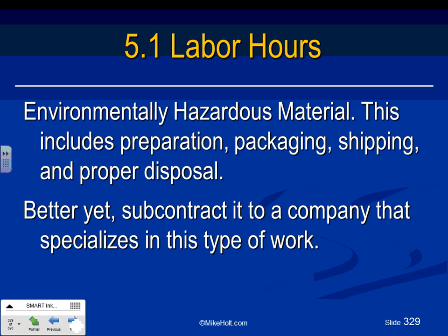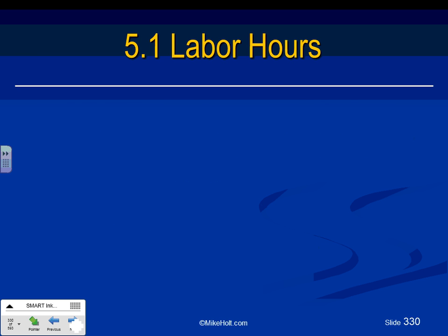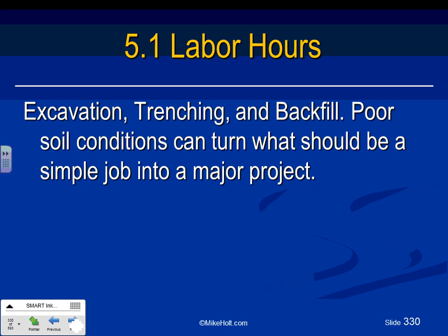This is just a suggestion: subcontract to a company that's smarter than you in this business, instead of spending so much effort dealing with asbestos, for example, which you're not qualified to do. So if there's any chemical hazard or asbestos hazard, you might have to put another subcontractor to do it. Excavation, trenching, and backfill can turn into a major project. You have to take into consideration, guys, that you're going to be digging a trench there. Do you know if it's going to be a rock bed down there? Can you go 2 feet in the ground? Is it going to be wetland? So with trenching, you might have to add more or less dollars, or even subtract it.